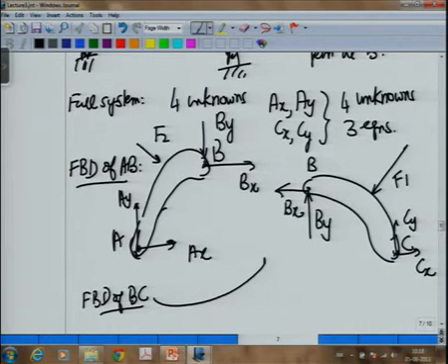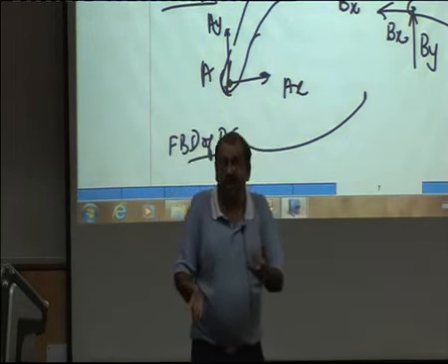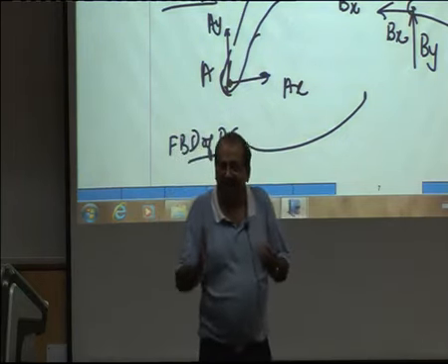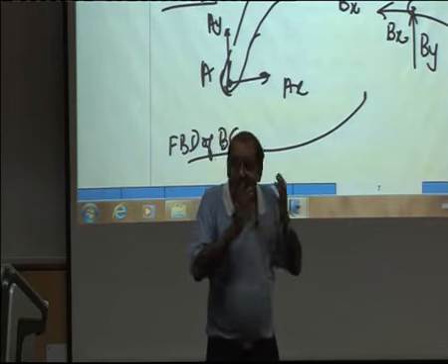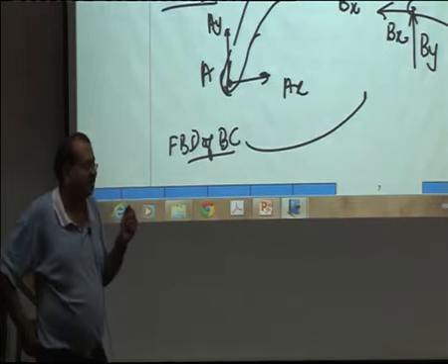Okay. So, now when I add the total number of unknowns in the 2, now I have 3 equations here, I have 3 equations here. So, totally I have 6 equations. And how many unknowns do I have? 6 unknowns. So, actually the system therefore is statically determinate. Now, what is the magic which made the system statically determinate? We can use this trick, we can break the system any point at any time and we will be able to get it. Will we be able to make any statically indeterminate system into determinate by this trick?